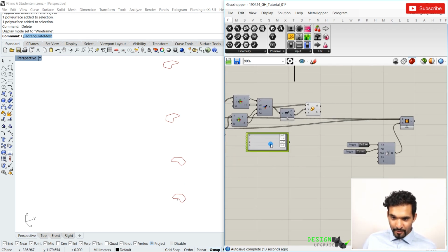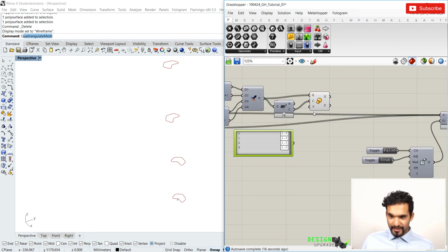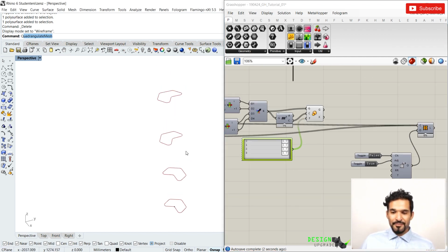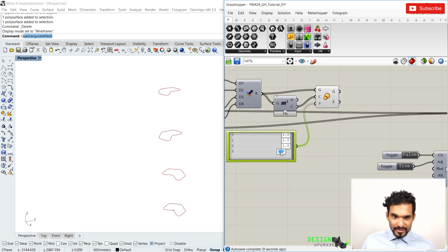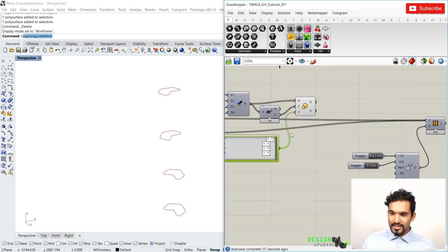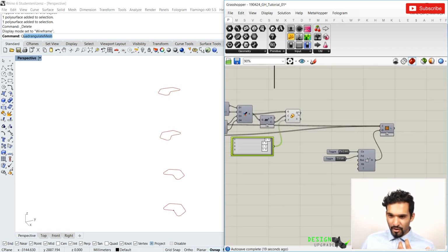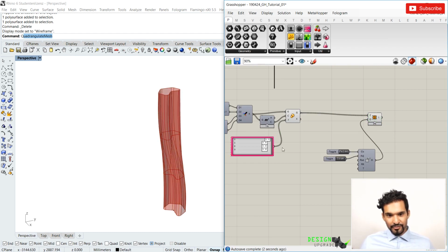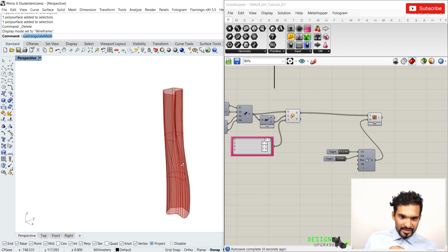So if I hook up now my gene pool into the scaling factor, and I know this can be a bit of a hassle to understand, but we are nearly there, we can see that this actually works exactly how we want. And now we can actually try to shrink our individual curves the way that we want that to be, right? So this is basically a design feature. Now we can put everything in our loft, and we can enable the loft. This should still work quite nicely.